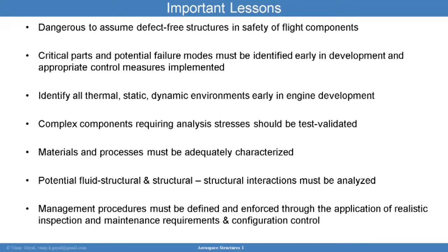We also want to identify fully all the environments you're going to see in service. The structure is going to experience perhaps thermal, static, dynamics. In this case, I'm talking about an engine, but it applies to everything. It applies to every single piece of structure. You want to make sure that all the thermal and static and dynamic loads are fully known. And if you don't know them very well, you want to put a factor that envelopes the loads.